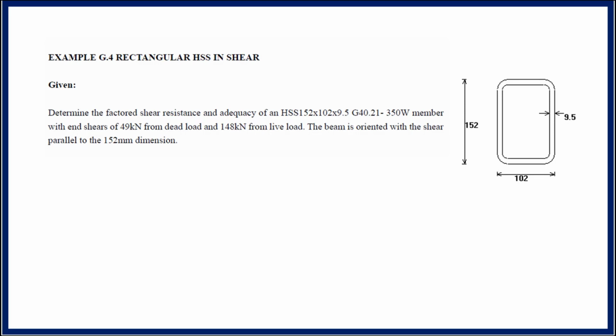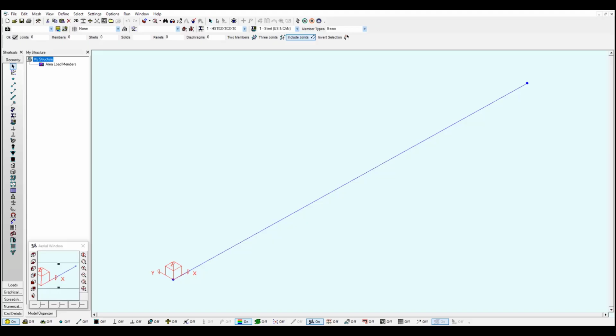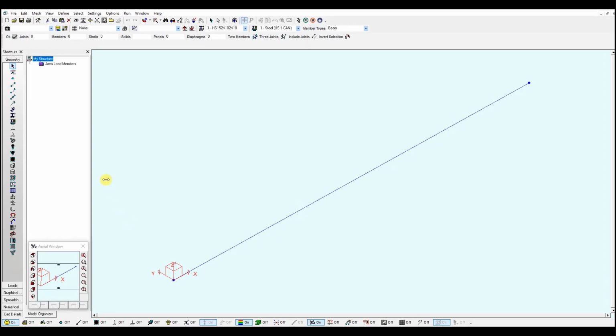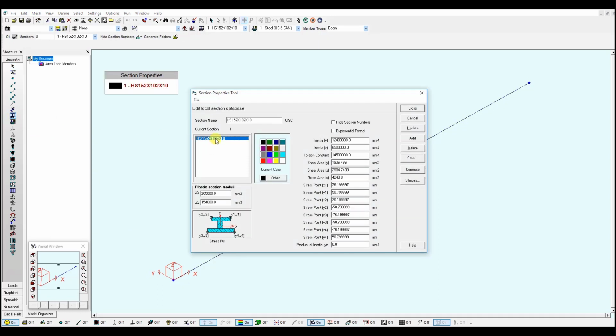What I'm gonna do next is to take the design load results from our analysis software, which is SFrame for this case, and use SPAT to code check this section. Now let's go and open the SFrame model that I have. As mentioned, this is a model I built before, so let's see some of its properties. We can check our section properties if we right click here and select our section.